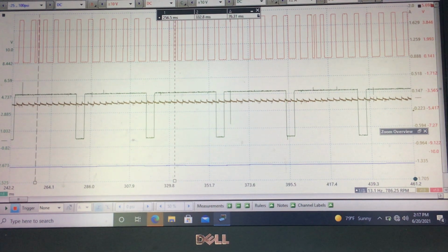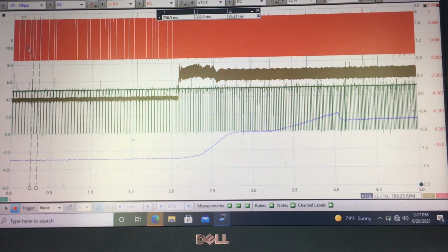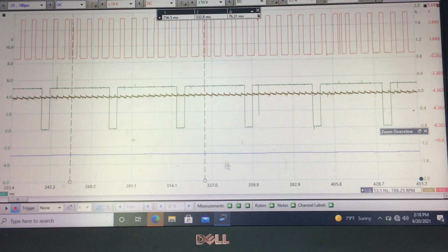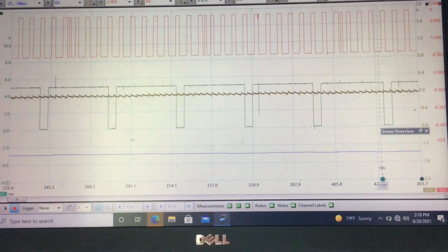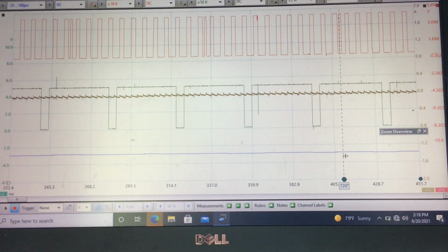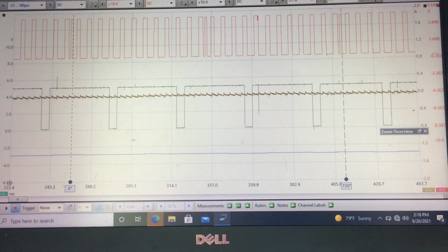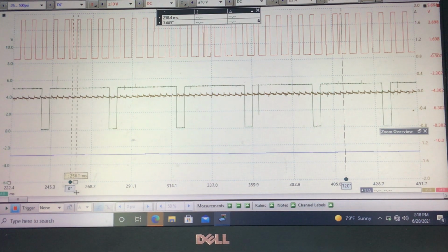Let's get a baseline. We're idling right there, and let's get our timing just for the grins. Let's see where we are as far as our timing, and we'll base everything there. I'll only make 2 timing advance checks during this whole video. We're going to concentrate on oil pressure. Here is our fire cycle, 720 degrees of rotation. And I'll base it from there to the first notch on the intake cam. Not really degrees before top dead center, but degrees of where the cam is, how far it is from that reference point on the crankshaft.